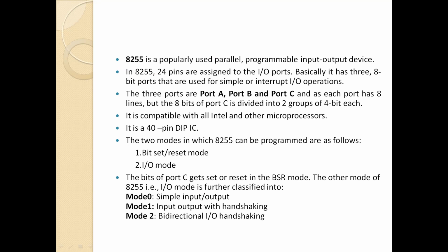Basically, it has three 8-bit ports, port A, port B, port C, and each port consists of 8 bit lines. Further, the 8 bits of port C are divided into two groups of 4 bits each. It is compatible with many microprocessors.